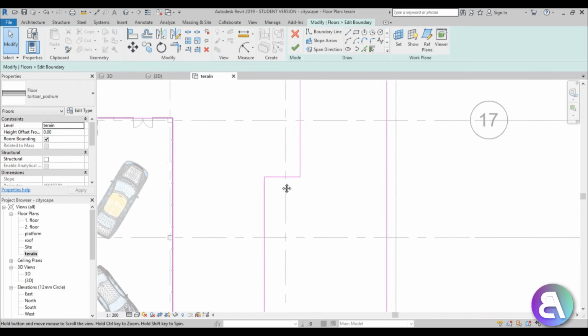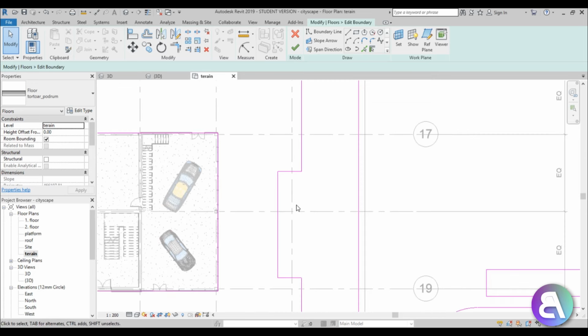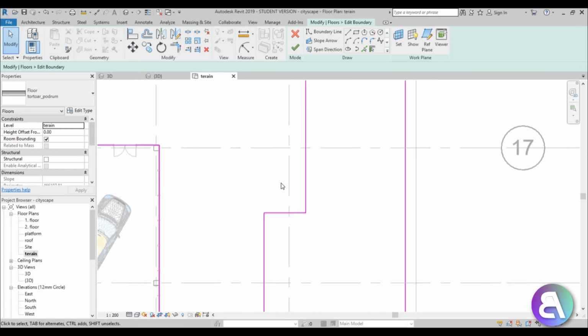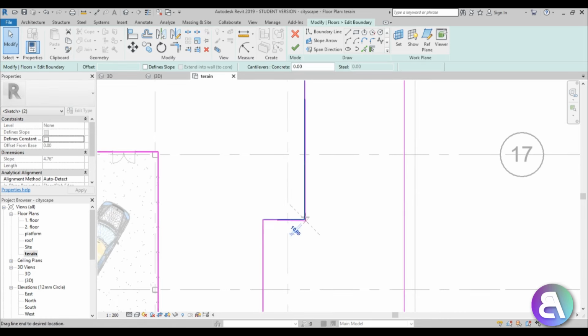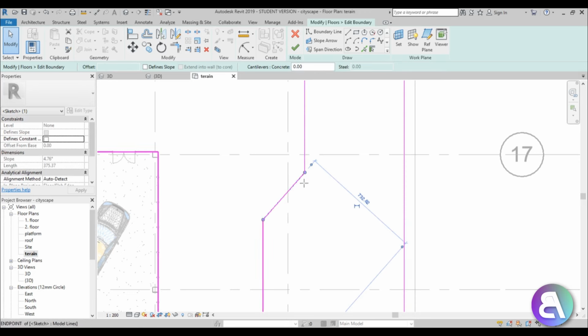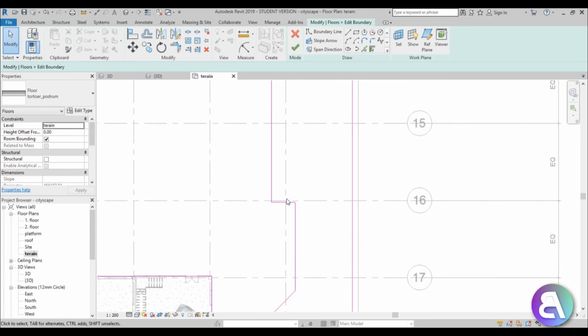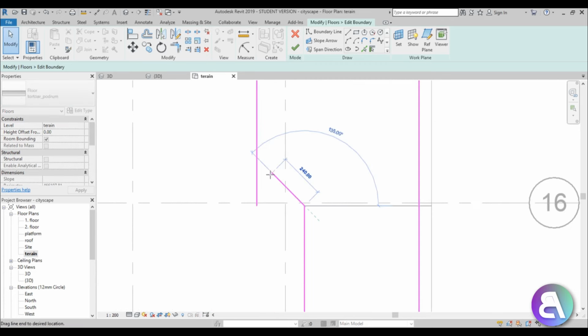First, for parking, it's quite difficult to get in a parking space like this. This is parallel parking. This is enough space for 2 cars, but to make it a bit more comfortable, I'm going to move this in such a way so this line is at 45 degrees. Let's set that to 45 degrees, and then let's just trim and extend. And let's do the same thing with this line over here.